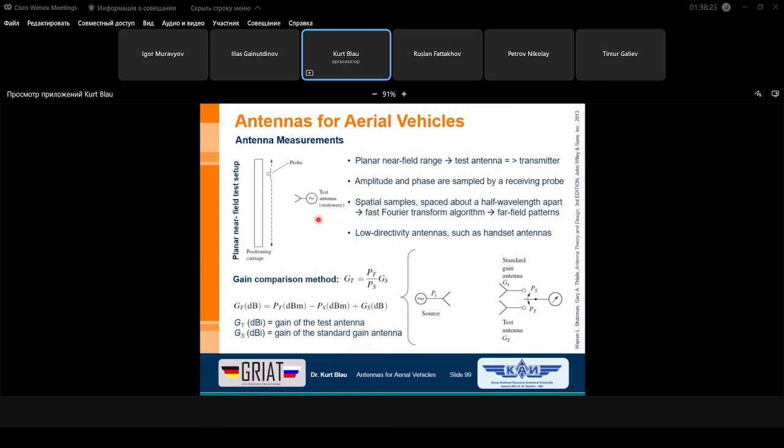Again, you have to avoid any reflection, but the near field scanner can also measure the backside of the antenna if you only turn it around. And now you can ask how it works. If you place the antenna very close to the probe antenna or to a probe system, then we never can achieve the far field conditions. We never can go out into the Fraunhofer region. This is correct, and you can see here how it works.